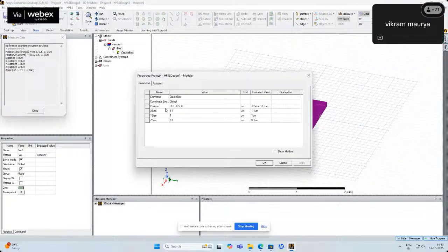Okay. Now, the coordinate system in ANSYS HFSS compared to CST is very different, and we have to understand the difference very clearly in order to make any unit cell or any type of structure, any FSS. So position is basically your start point. Position is basically the base from which the structure is started.